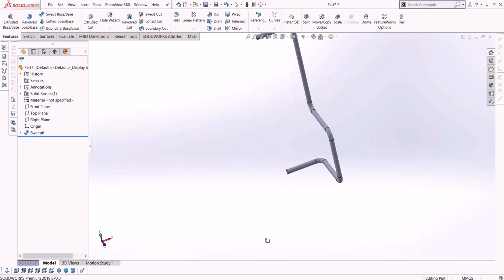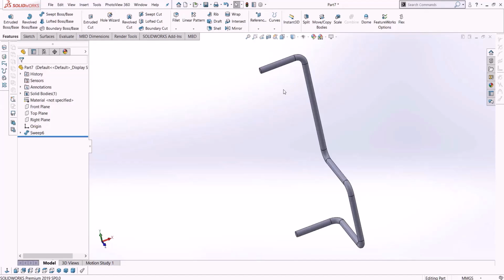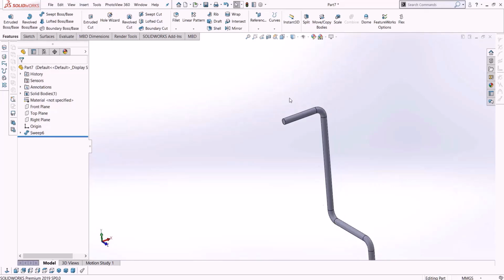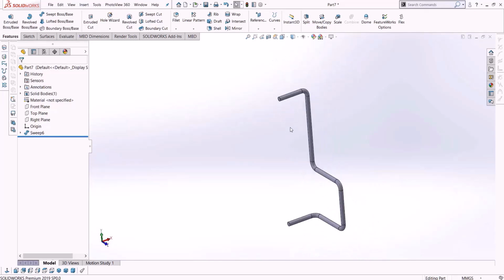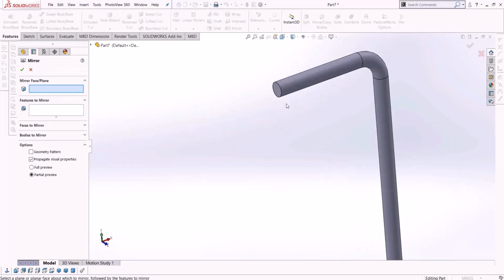Usually for symmetrical shapes, we draw half of them and mirror the rest. Of course, it depends on your modeling skills. You might find it easier to draw the whole thing. Each modeling process has its own tricks with different software. For example, it might be easier to create a 3D shape with a sweep and fillet. I always like to start by creating from the front view. Some people, for instance, start from the side view. It's all experiential. We take the fillet and want to apply it relative to this plane.